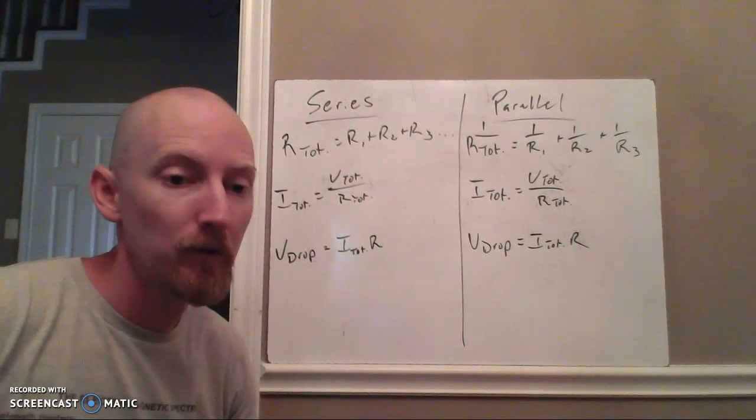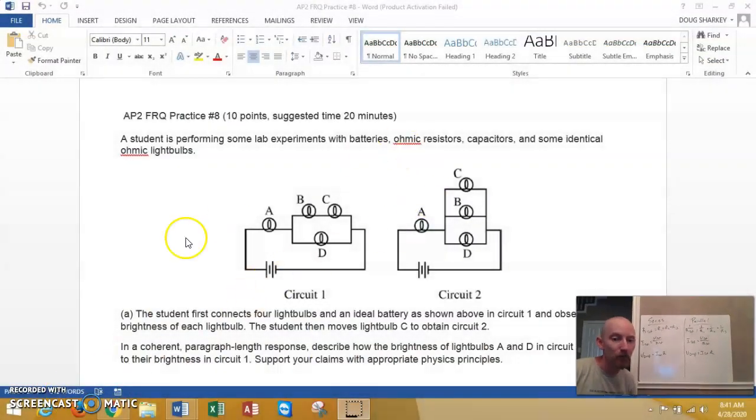So when we look at this circuit right here, these two are in series, which are in parallel with those two. These two are in series, so you would add these up, R1 plus R2. That would give you more resistance here, which means you'll have more total resistance for the whole circuit.